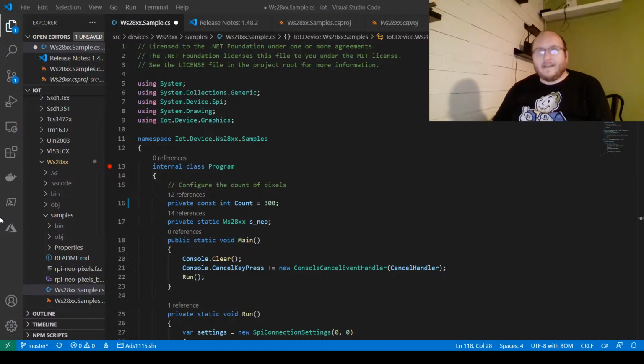And if you go ahead and connect the red pin, it will back power the Pi. So you need to be careful with that to make sure you don't accidentally back power it with too much power. Because the Raspberry Pi does not have the power protection on its GPIO pins. It only has it on the power input through the USB Type-C cable, since we are using a Pi 4 here.